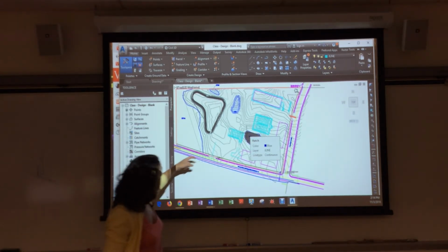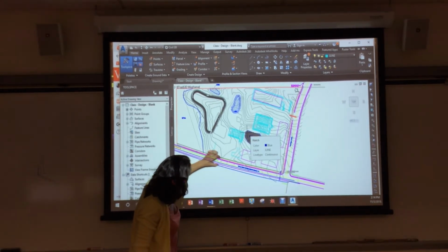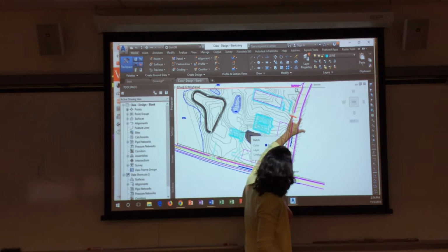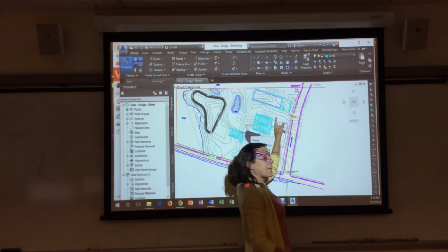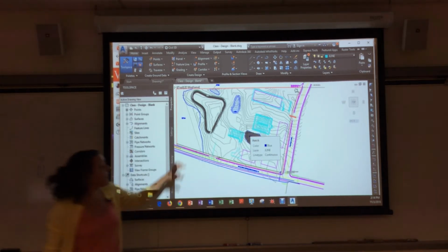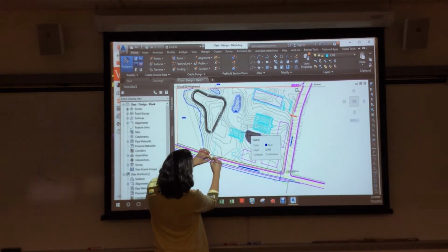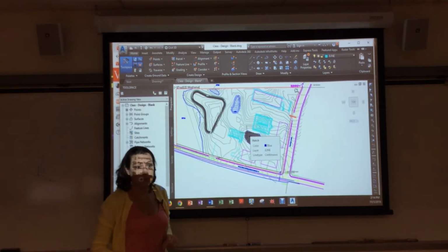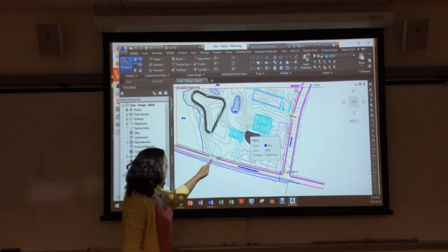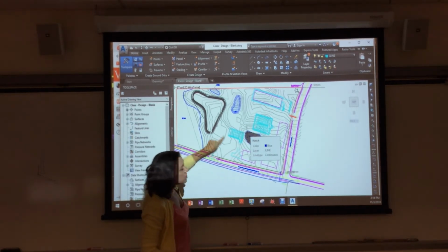So you have to, from this black line right here, which is our right-of-way line for this road, and this black line, this road, water has to come back to us and not to the street. The storm pipes in this section of the road should have accounted for the sizing there. Right? So instantaneously, as soon as you get to this point here, you need to start sloping downhill.